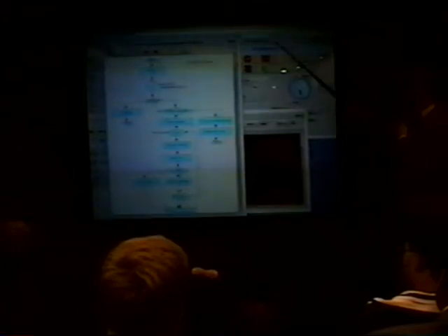In addition to performing simulation analysis, we also have the ability to go in and profile and look at different characteristics of our designs. As an example, we can look for unreached states in the state machine, or we can look for undriven signals that might exist inside the design. We also have the ability to profile and look at the different activity levels within the circuit. So for our flowchart, we go ahead and hit the OK. We'll see a histogram that shows us the amount of activity that occurred within that particular design.